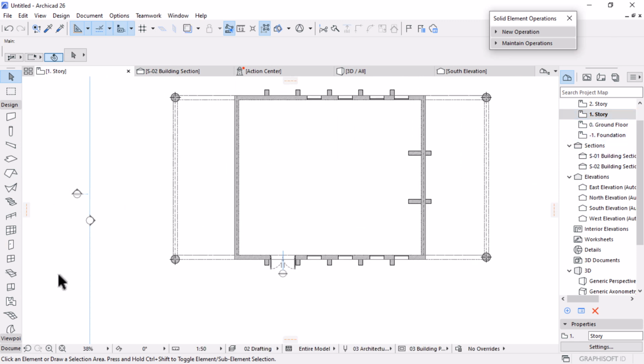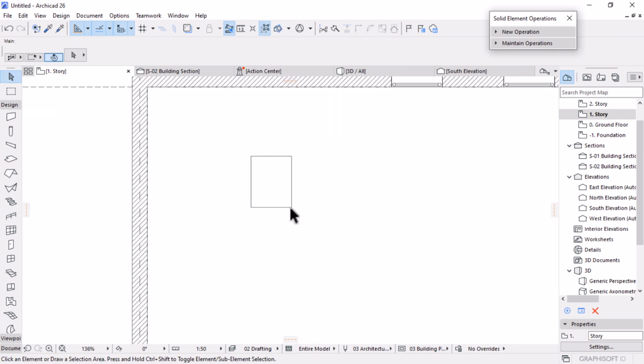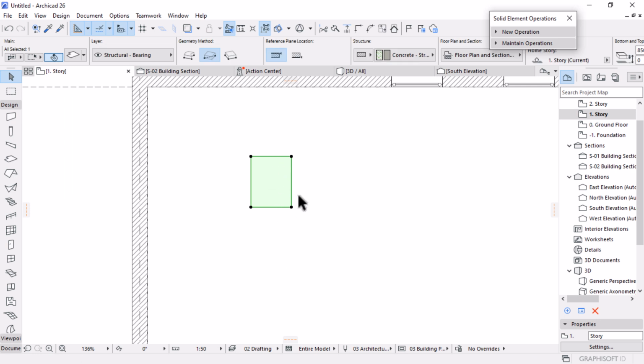Okay, so I'm going to open this floor, first floor, and then I'm going to draw some slabs here that I'll use to cut off that. Okay, I could use also openings, but the opening tool will take me ages to finish. So let me use a slab. I'll just use a basic tool and then just draw a slab of maybe 800 by a meter. Shoot, a meter is too much. That will be too much.